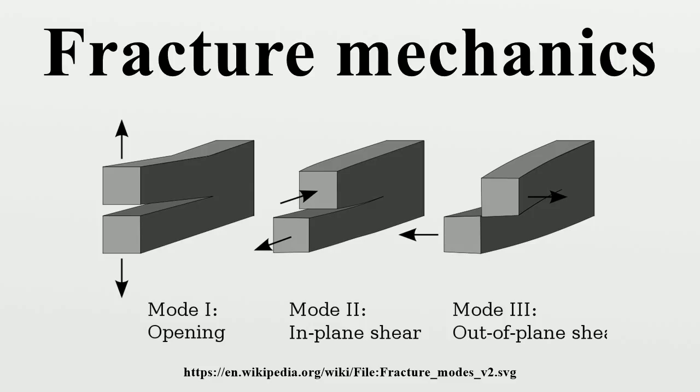The value for engineering alloys is 100 mm, and for ceramics is 0.001 mm. If we assume that manufacturing processes can give rise to flaws in the order of micrometers, then it can be seen that ceramics are more likely to fail by fracture, whereas engineering alloys would fail by plastic deformation. Crack-tip constraint under large-scale yielding.